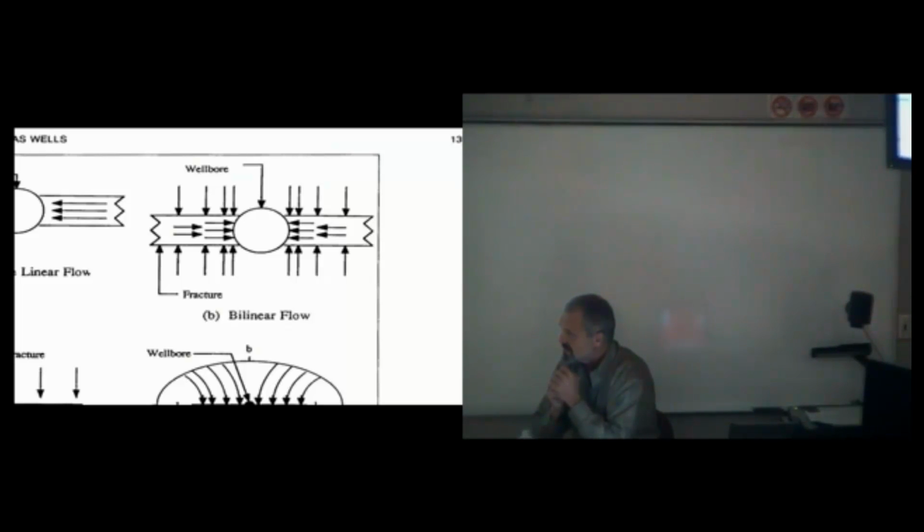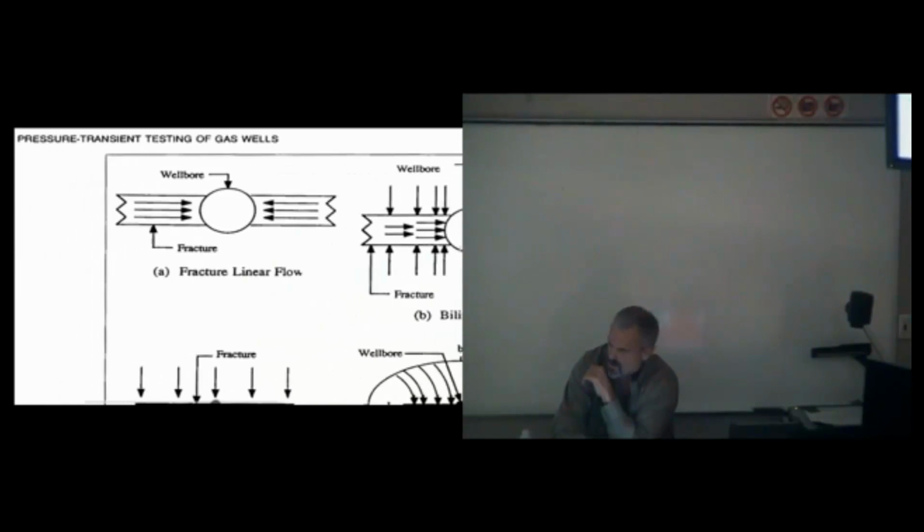So you're in linear flow whenever you're blowing back a well, producing any frac water? The first second when you turn on the wellbore, you're in fracture linear flow. The only thing that's going into that wellbore is out of the propped fracture. Think of the comparison and the permeability of a sand pack. So that's fracture linear flow.